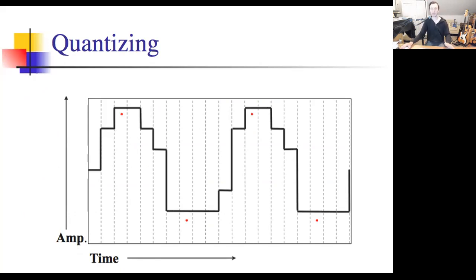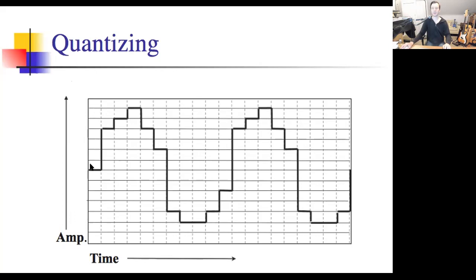Those two concepts, sample rate and bit depth, are key to understanding analog to digital conversion, the quality of digital audio, and also the inverse process of digital to analog conversion, which we then hear through pressure waves. So a higher bit depth is going to give us a higher resolution of potential amplitudes. And a higher sample rate is going to allow us to get little options in between every one of these points. And once again, more analogous to the original signal.